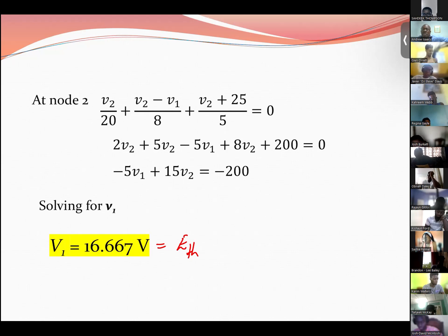So we go back to the notes, and so that was just step 1, where we find the open circuit voltage. All right. Step 2 in the process is that we now need to find the Thevenin resistance. And the Thevenin resistance, as we defined it earlier, is the resistance seen looking into those terminals when the sources were replaced by their internal impedances.